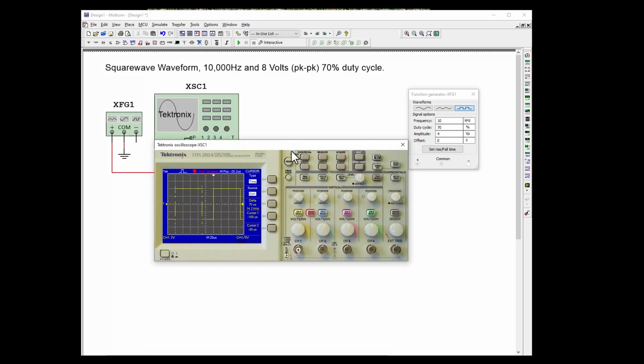Let's bring it back. And let's go ahead and continue to move our cursor. So let's move, come on, there we go, and then move this guy over there. And 29.4 microseconds. I could dial it in a little bit, but it's basically 30. So that's how you use cursors.